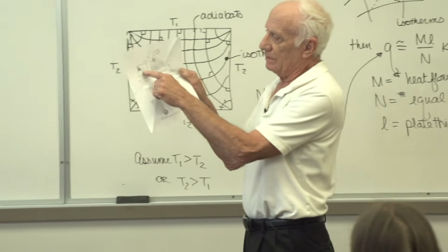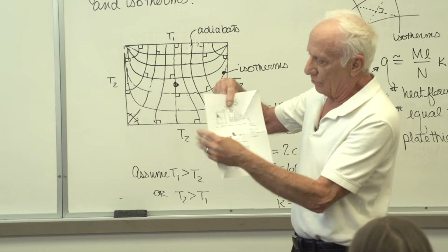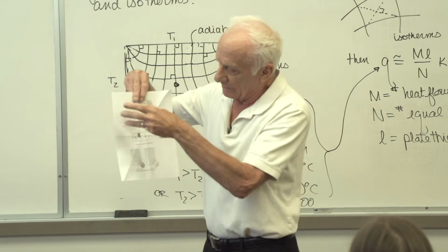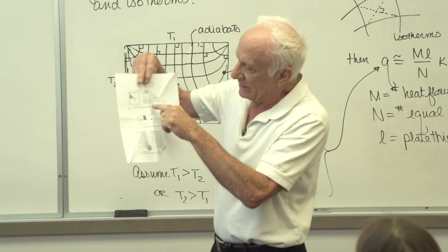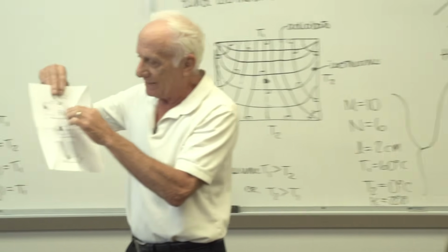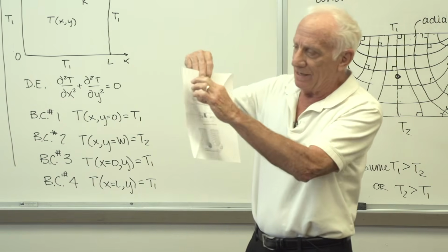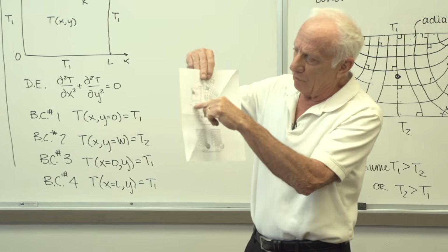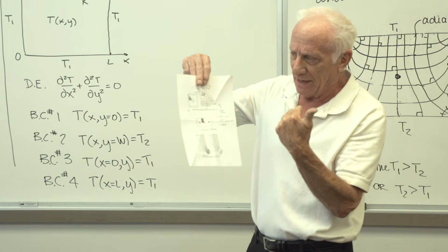Here's a square plate with a square hole cut out, at 45 degrees off from the square plate. You can see he checked for, do we have curvilinear squares? Yeah, really good. You can do the whole thing, but since it's symmetrical, you can just take 1/8 of it and then multiply Q by 8 when you're done.